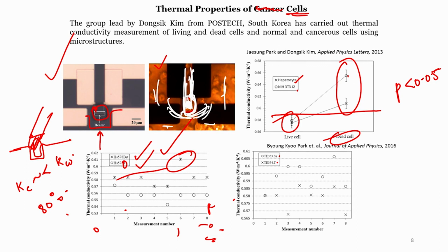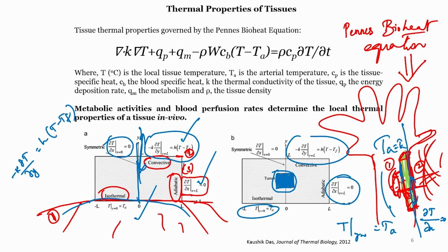So this is how we can measure the thermal conductivity of a single cell. You understood the challenges of not letting the thermal energy leach to the surface, so we have to limit it to a very small dimensional space. How do we do that? We use the micro heater with an AC wave of very high frequency, say 50 kilohertz or 100 kilohertz, so that the heater coil heats and cools and does not let the thermal energy transmit beyond the single cell. It stays within the cell, and then we use a 3 omega method to detect the temperature changes and thus measure the thermal conductivity.